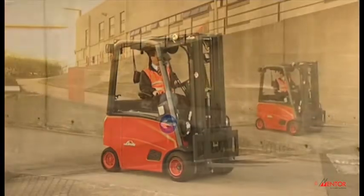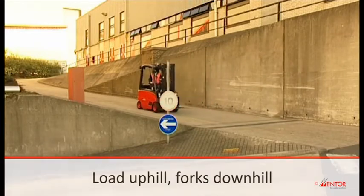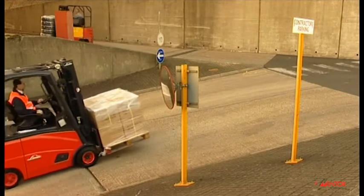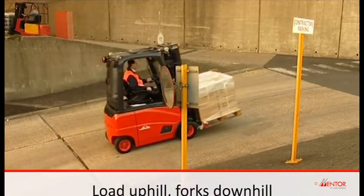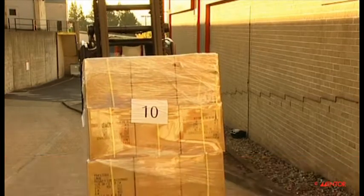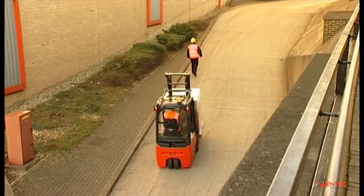Always look in the direction of travel, which means when traveling uphill, you will need to be looking over your shoulder. When you are driving with a load, your fork should always be facing uphill, which means when you're traveling downhill, you will need to be looking over your shoulder. And if your view is obscured by a large load, it is recommended that you use a banksman.